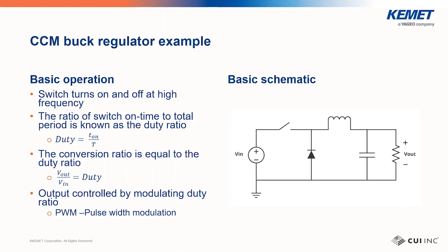This feeds into an inductor followed by our output capacitor and load, which form a low-pass filter. The low-pass filter blocks the high-frequency square wave from getting to the output and ideally only lets the average or DC value in. The average value can easily be calculated as the average amount of time that the switch is on, which is equal to the on time divided by the total switching period, times the input voltage. So, for example, if the switch had equal on and off times, the average voltage of the square wave that is applied to the filter would be half of Vin.